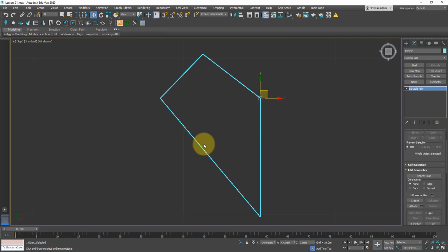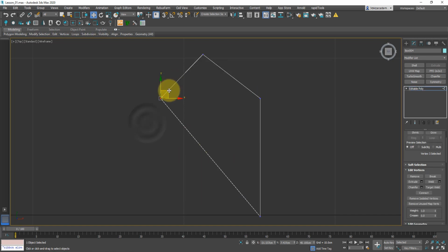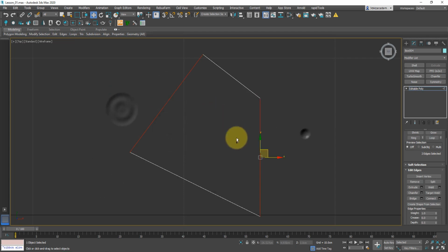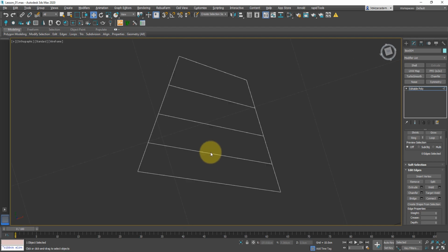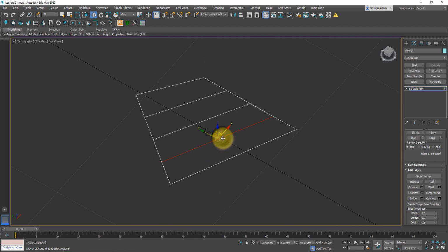What you also noticed is that I freely created and deleted a lot of those vertices. So let's, for instance, create a few extra lines. I'm going to select those 2 opposite edges, add a few connections, and we're going to explore the difference between remove, delete, and pretty much split.